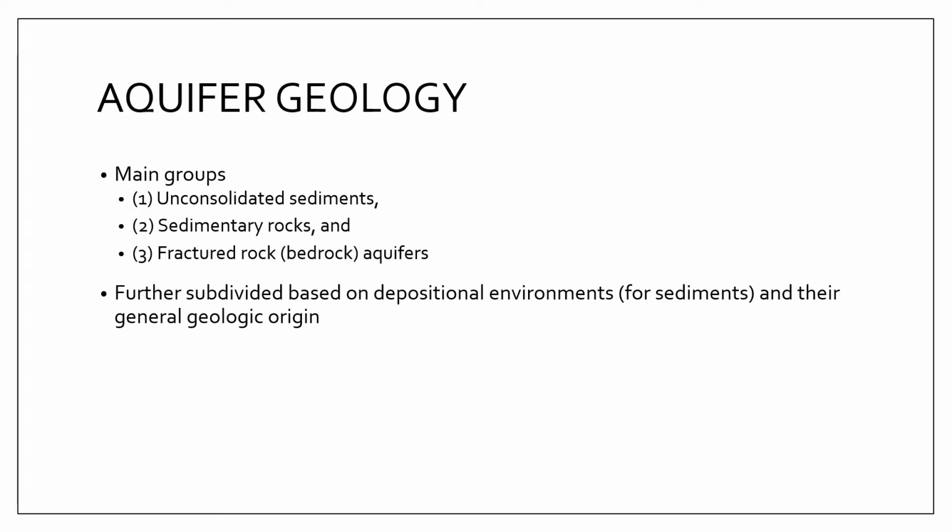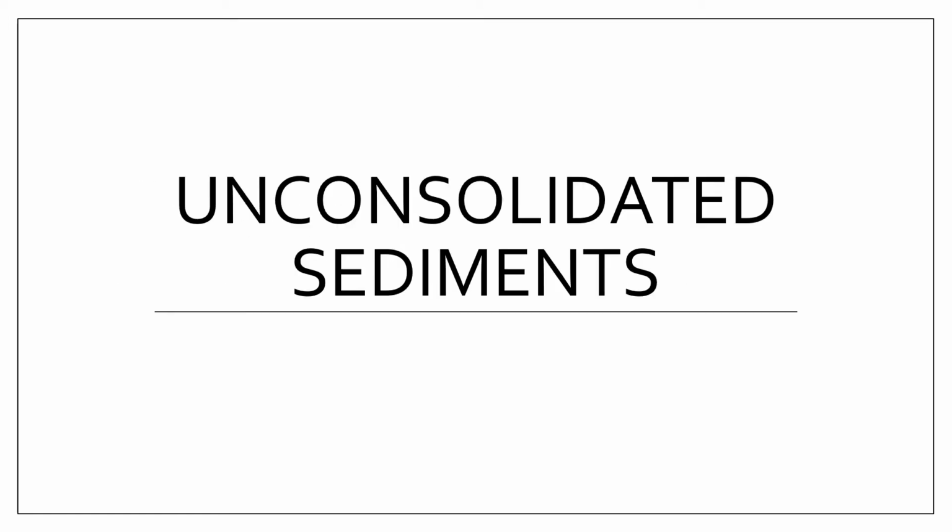So if you're expecting a fine or low energy environment, you're expecting fine soils like silts and clays, and from there you can expect that your aquifers may have low hydraulic conductivity. Or if you are talking about high energy environments like mountains and alluvial fans where you can have sand and gravel, you will be mostly expecting materials with high hydraulic conductivity, right?